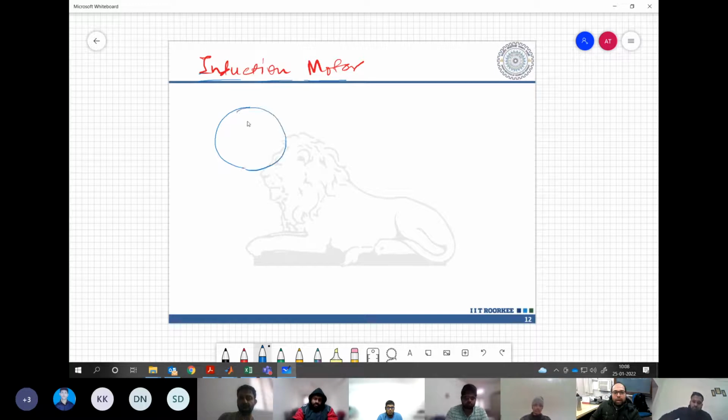In a DC motor, let's say we have the field present on the stator, and the armature is rotating. We have a certain current direction given to the coil. Let's say this north and south pole arrangement is there. For a particular direction of current, this field can apply torque only in one direction. So if the field is in this direction, north to south, and the current is going inside, how will the torque be? On which side? Can you tell? Either it will be left or right, right? Which one would it be?